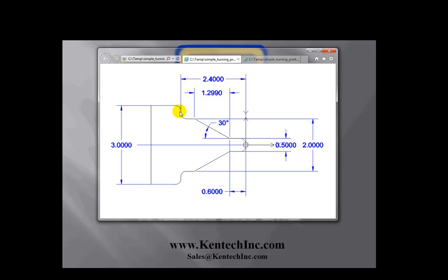Inside the software we're going to create a roughing toolpath which is going to rough along the radius, and in this case rough along this taper, and then come back and do a semi-finish and finish cut if we so desire. So it's a very powerful menu, and as I described, each of the elements that we input is going to have a vertical line, a horizontal line, and three different corners. Let's take a look at the menu and get started creating the program.